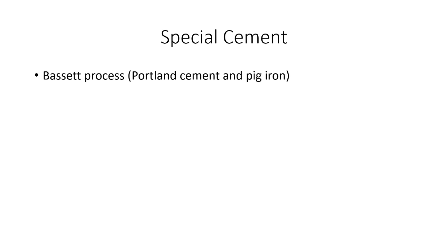The clinker is allowed to pass to the other end of the kiln and to the cooler. During this process, a reducing atmosphere is maintained in the kiln. Okay, no oxidation is allowed. So in this way, along with Portland cement, pig iron is obtained. Means due to the reducing atmosphere, this iron does not get oxidized. So we get the side product of pig iron.